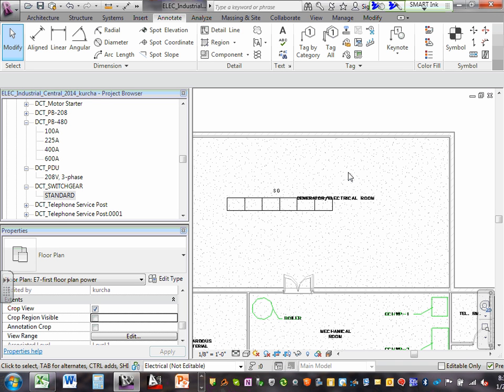Okay, so I dropped my switchgear here. I want to remind you guys I'm going to have multiple panels. So let's go talk about panels. How I'm going to lay out my panels. Why do we put it in the middle of the room? Because we have the whole room for electrical. Switchgear needs front and back access, so you put it in the middle of the room.